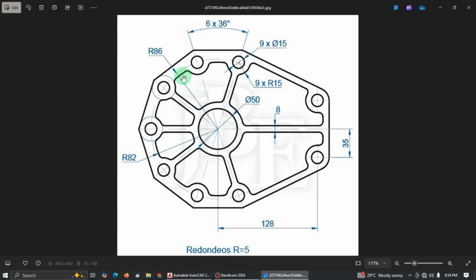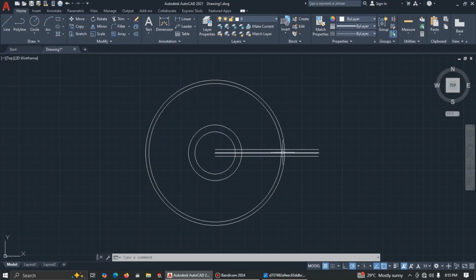All right, well done. Now we need to draw a line for the angle. Now I'm going to show you something. When you are drawing in AutoCAD, AutoCAD always reads the angle anti-clockwise, so it will start from here and then move this direction. So here would be 0, up to here would be 90, then from here downwards would be 180. Okay, so from here downwards to this side to 360.